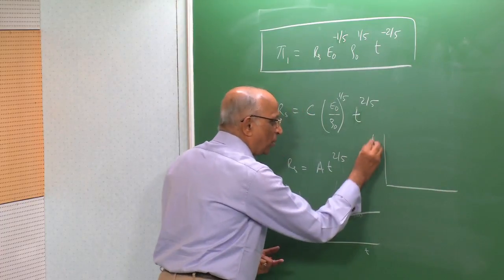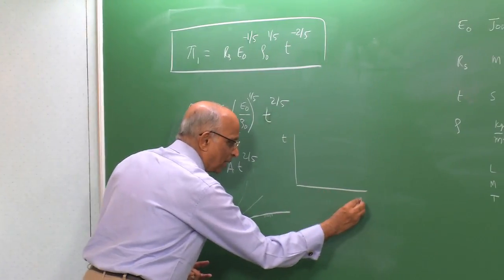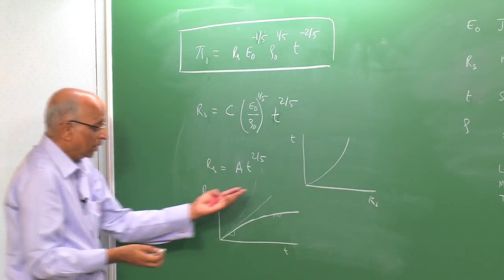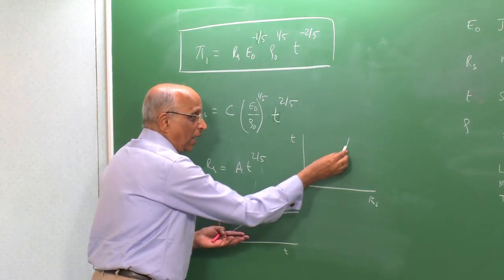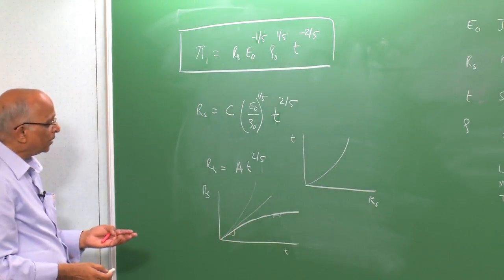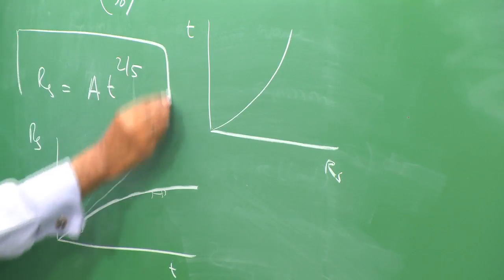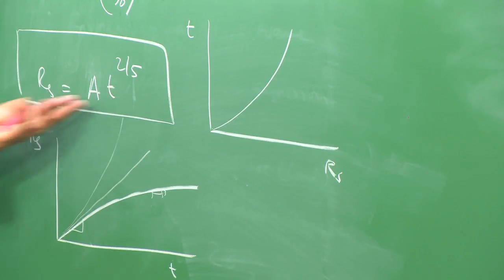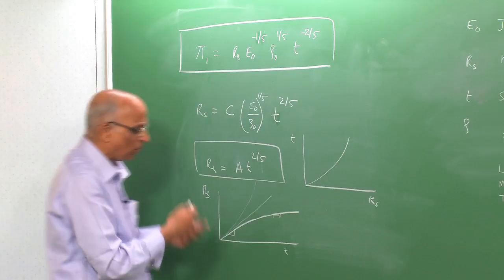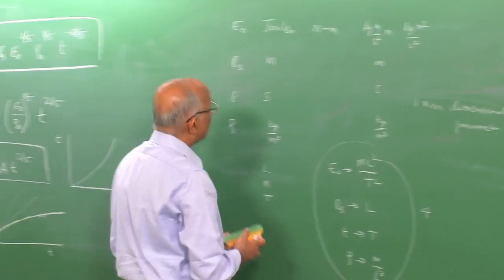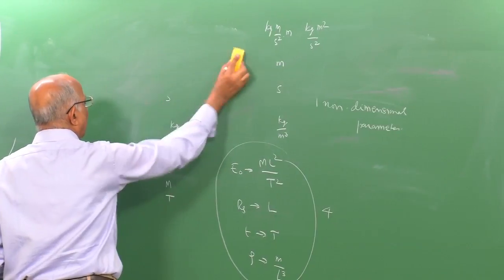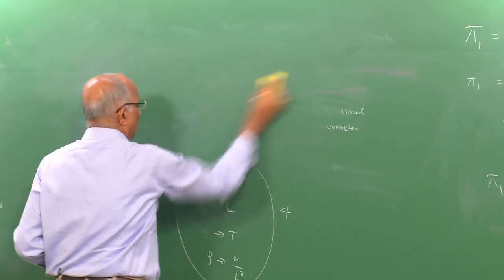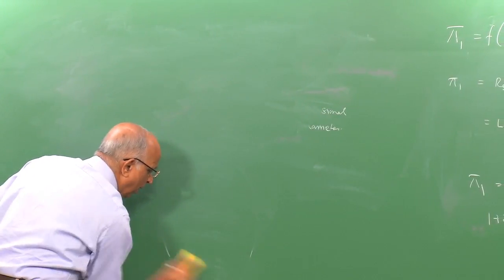Rather, if instead of putting it in this figure, I put it in the form of the streak diagram which we drew earlier, namely t over here and the distance Rs along this, I get a figure like this, which is what we thought initially. It starts off at a high velocity and ultimately it becomes an acoustic wave. Therefore, this dimensional analysis has been able to give you the radius of the shock at a time t, and now using this, let us go ahead and do some more analysis, and also discuss how Taylor was able to guess the energy release in the bomb explosion over Hiroshima and Nagasaki.